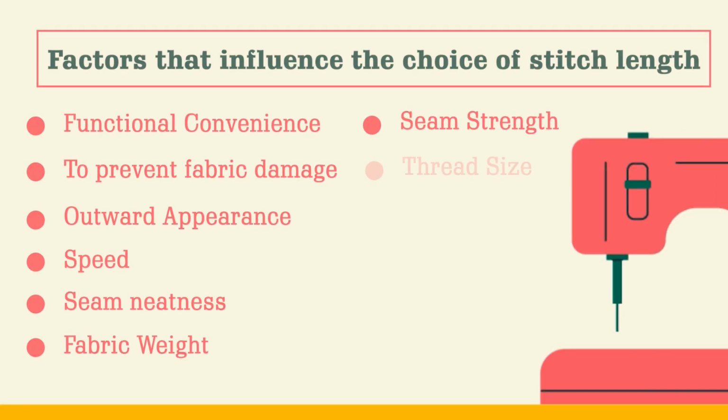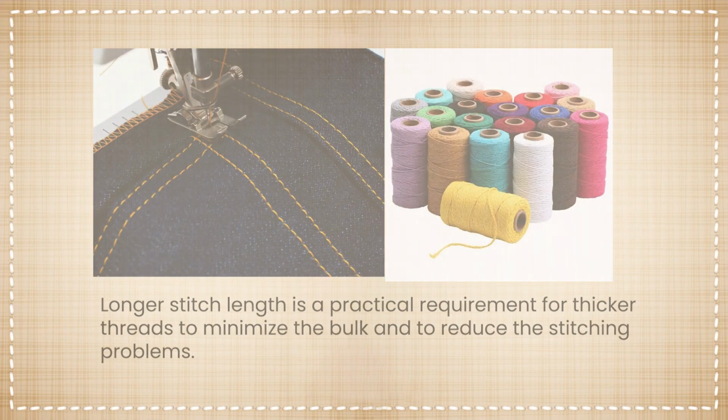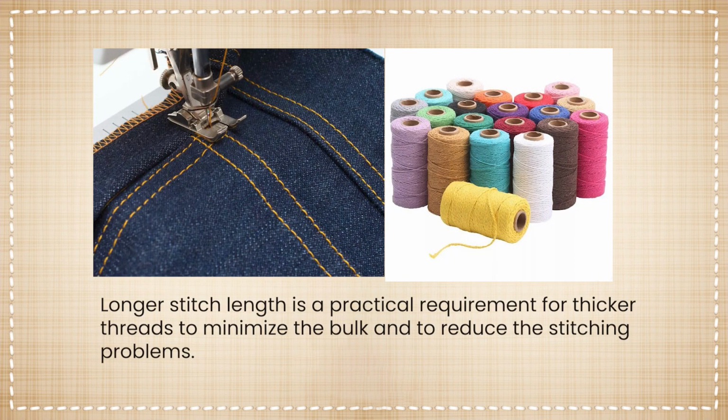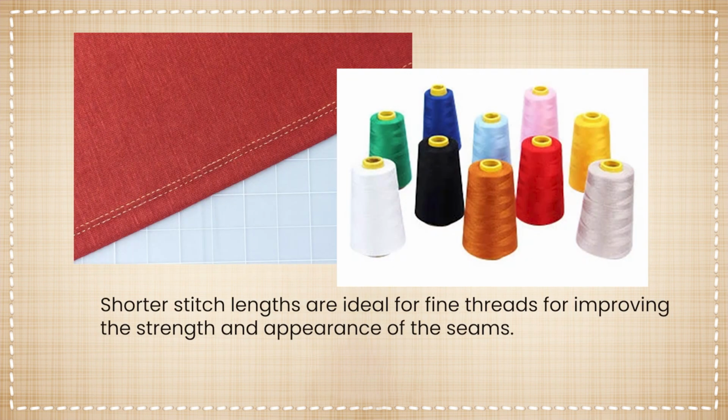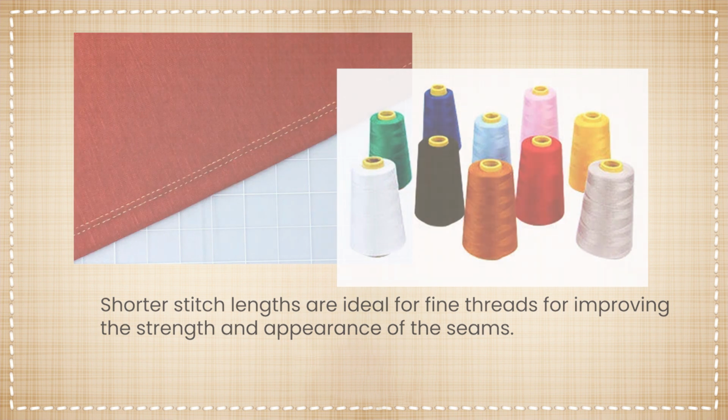The thread size should also be taken into consideration. Longer stitch length is a practical requirement for thicker threads to minimize the bulk and to reduce the stitching problems, whereas shorter stitch lengths are ideal for fine threads for improving the strength and appearance of the seams.